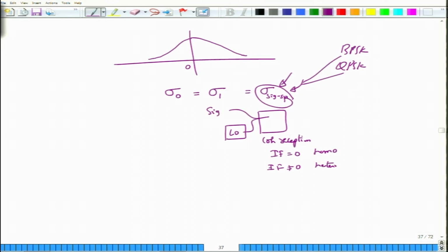And again in these cases the dominant noise comes not even from the amplifier, but rather from the local oscillator that is used. Okay. So, we have these noise statistics being different for different modulation systems, and one has to take this into account when you are dealing with BER calculations.